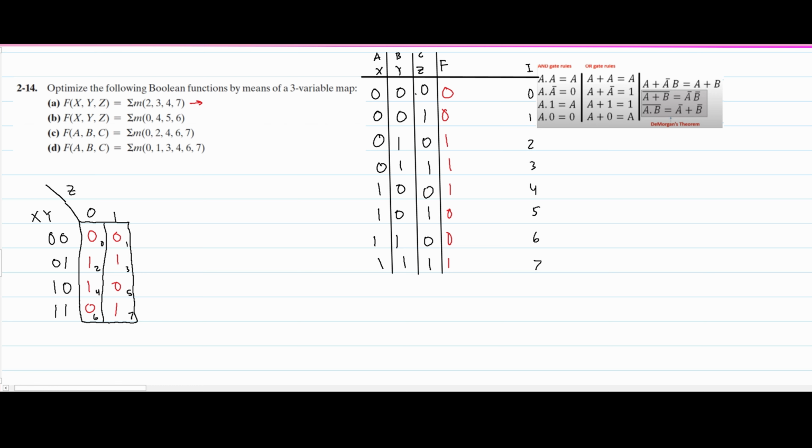Well, we know in a K-map, we can look up and down, and we can look left and right. So I'm going to start this off with indexes 2 and 3. We can see they're right next to each other, like this, so let's analyze it. We can see that it's going to be a 1 no matter what column of z it's in. And so we are going to disregard z when we are looking into making our Boolean function.